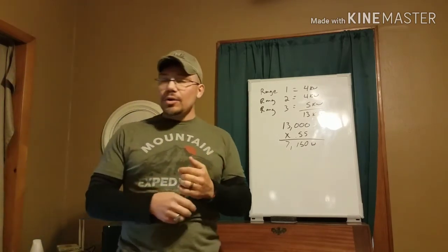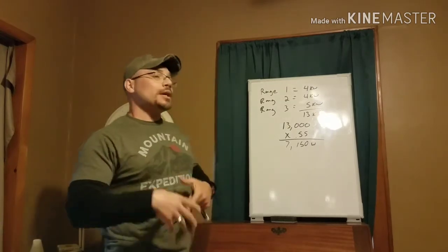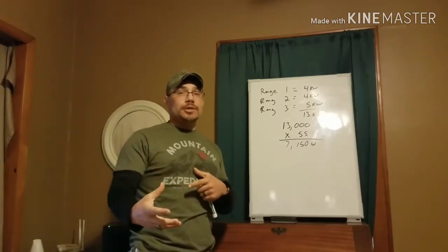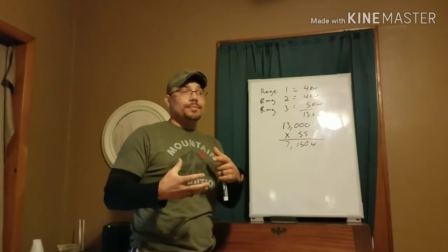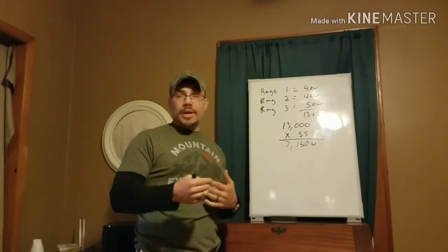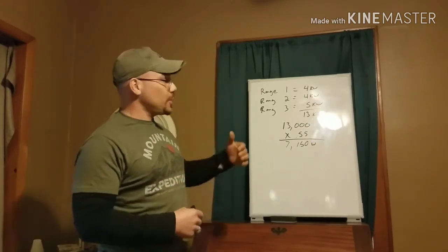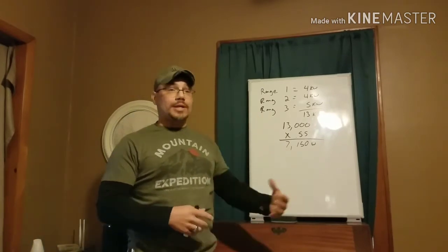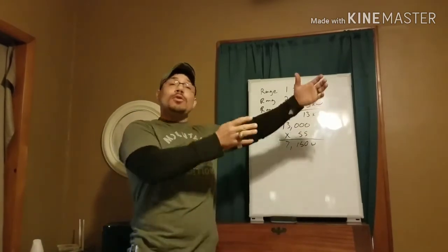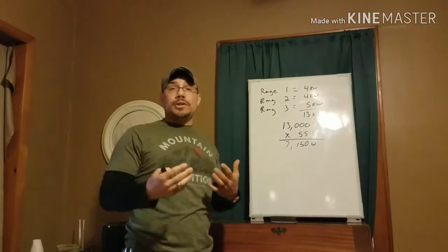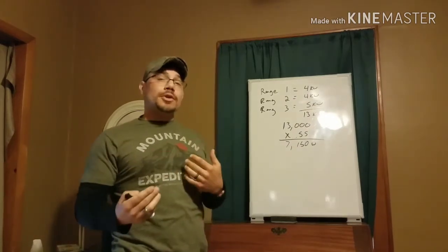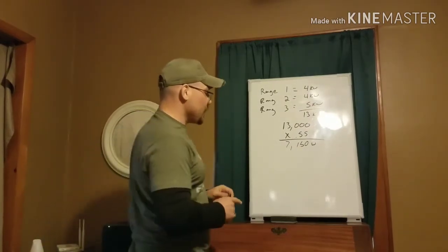Okay, now one thing we need to do now is, let's say in a residential setting, a lot of times you're only going to have one range circuit, right? And so sometimes it's a single range, sometimes it's a range and a counter-mounted cooking unit and a wall-mounted oven, and they're all on the same circuit. If they're all on the same circuit, it's got to be done a little bit differently.